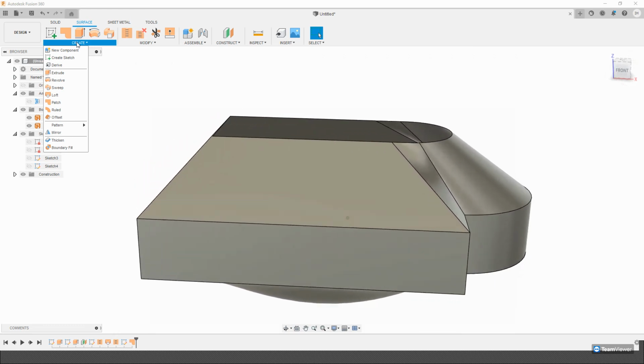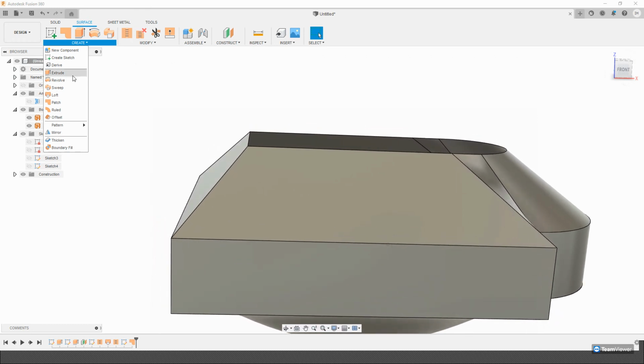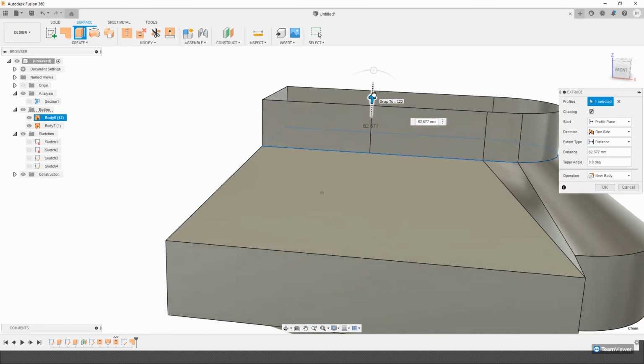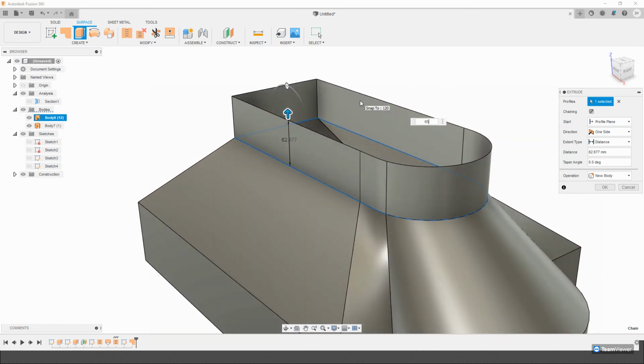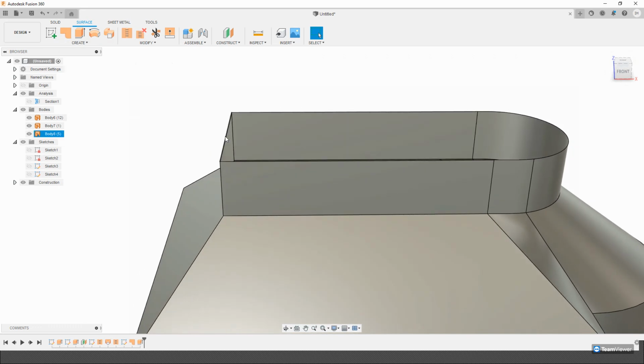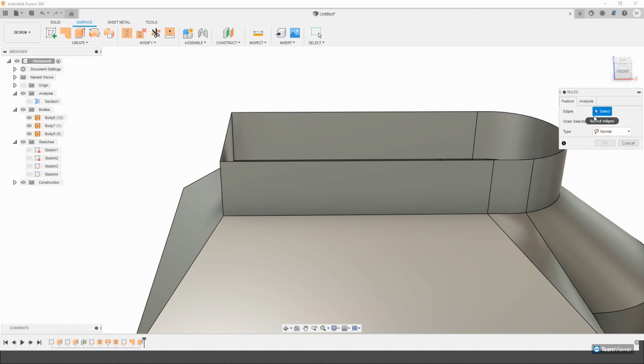Similarly, we can use a ruled offset. And remember how I said that we can have an extrude where you take a line or a sketch and you extrude it in the principal direction that is perpendicular to it. So for example, like so. You can also have a ruled surface where you can take a line and extrude, I say extrude in inverted commas, because you're not actually going perpendicular anymore, but you can go parallel to the plane that the line is drawn on. So if I use a ruled surface, I can say, let's uncheck selection.